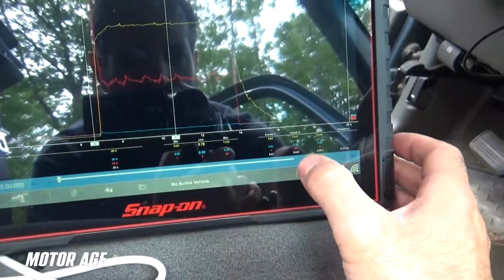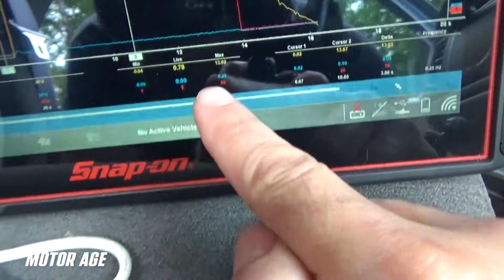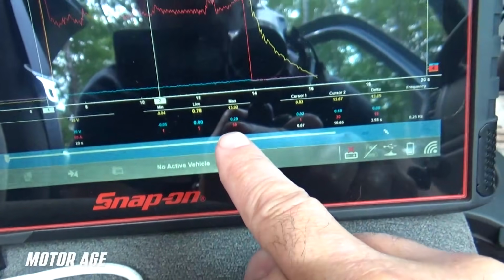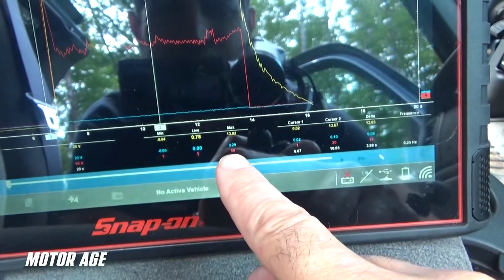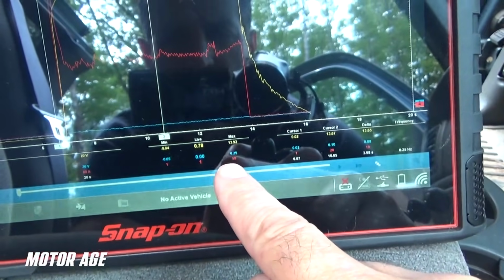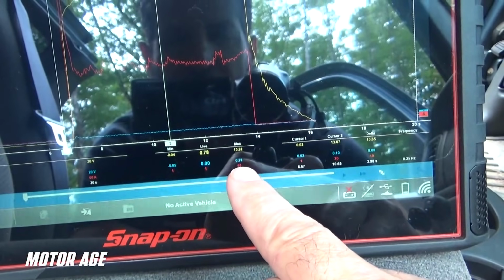And our amperage is about 18, 19, but more importantly, look at our inrush current. Our inrush current is down to about 60 amps. On the original motor, it was over 70 amps. So what we're going to do now is let the motor run for about 5 minutes, just like we did before. And we're going to measure temperature, both the connector and the motor armature at the base of the motor assembly itself, and see the difference.